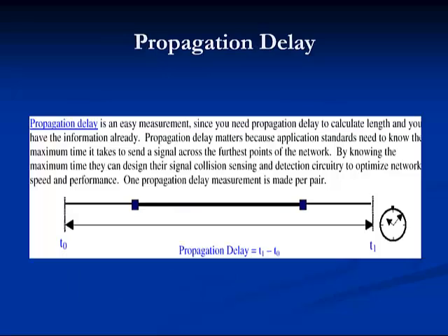Electrical signals travel through a cable at a constant speed, expressed as a percentage of light speed, called nominal velocity of propagation. For unshielded twisted pair cables, NVP is usually between 60 and 90%. The manufacturer of the cable controls the NVP value because it is largely a function of the dielectric constant of the insulation material. The difference between the time at which a signal starts down a pair and the time at which it arrives on the other end is propagation delay.